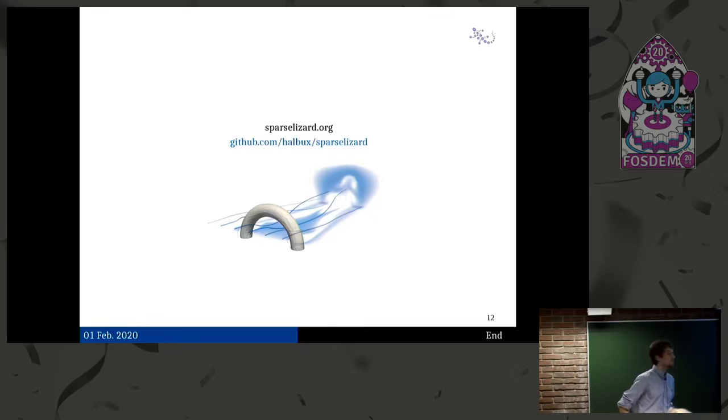The only limit for now is that I call PETSc to call MUMPS, because MUMPS is efficient in solving the algebraic problem. For now, PETSc doesn't call the new version of MUMPS, so it's limited to a number of non-zeros in the matrix of less than about 1 or 2 billion, which limits 2D problems to 50 million unknowns.